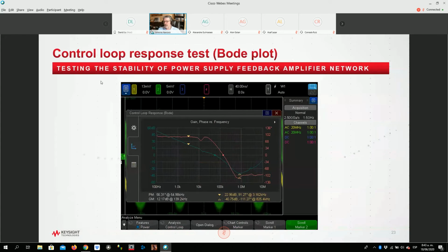This is an example of our Bode plot capability, which we'll go into deeper in a couple of weeks. And you can see at the beginning of our sweep, when we're measuring gain, I'm able to measure 53 dB. Now, a lot of people say, no, scopes can't measure anything with that much dynamic range. Actually, for our Bode plot capability, we specify up to 80 dB. I've been able to measure in a low noise environment upwards of 100 dB. So that's pushing what a network analyzer can do.